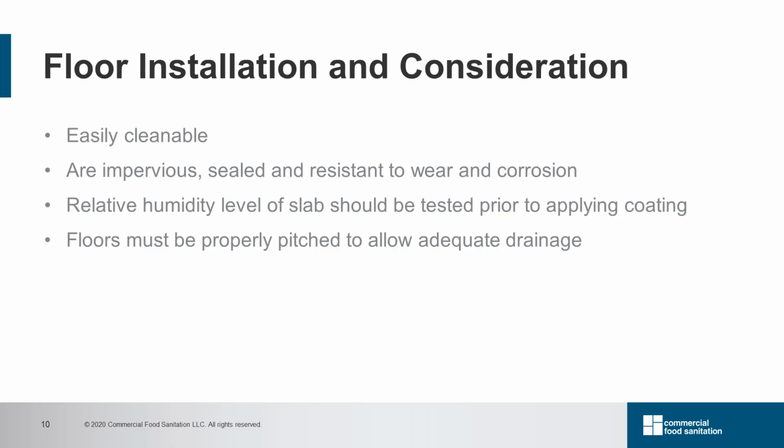During the installation of the floor, it is necessary to pay attention to the control of the moisture content of the cement base. If the moisture content is too high, deformation of the foundation will occur and the integrity of the upper coating will be affected.